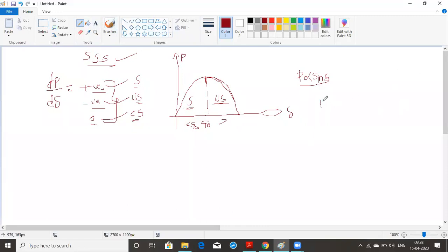That actually depends not on this delta, but on the excitation voltage of the generator E and the terminal voltage of the load V divided by the reactance X from the generator to the load side. That is what gives the maximum power. We need to deliver the maximum power. So it is directly proportional to E, directly proportional to the terminal voltage V, and inversely to the reactance. E is the excitation of the synchronous generator. V is the terminal voltage at the load end. X is the transfer reactance from the sending end to the load end, from the generator side to the load end side.